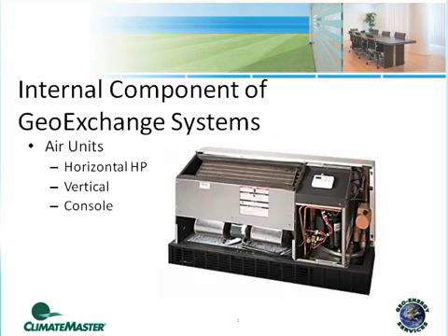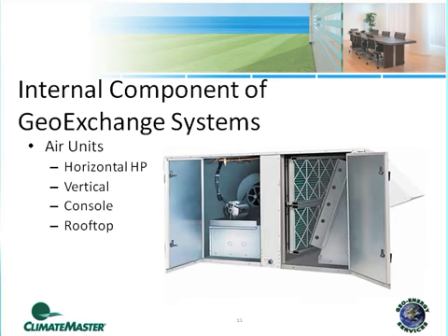Now, the next type of unit that you might see is what they call a console heat pump unit. This is a direct room unit, so you might see these typically in your hotel or motel configurations in the outside wall, or you might see these in spot private offices, things of that nature. I do caution people about using console units, though, in a new construction project. Because they are direct mounted units in the room, they do have a tendency to be a little bit noisier, because the compressor and all the operation is right there in the room. Now, people who like white noise, it may be a perfect opportunity.